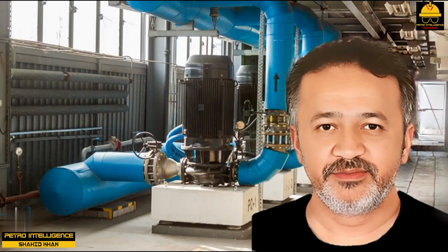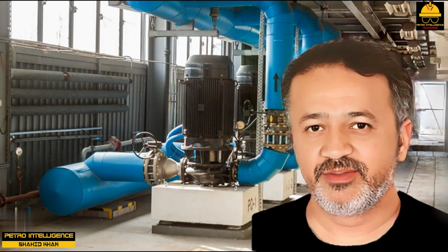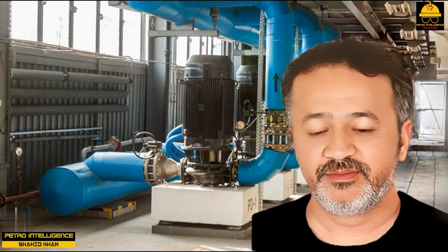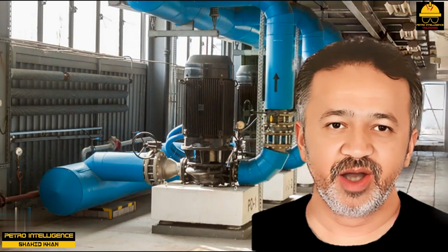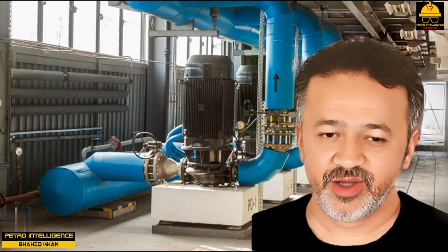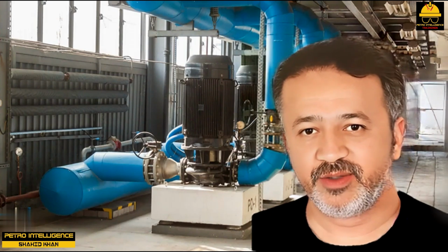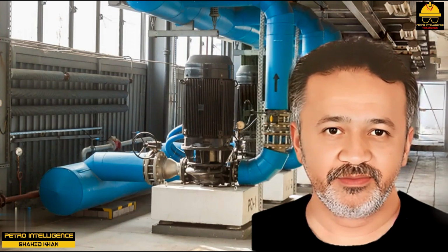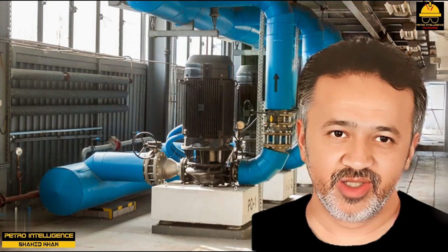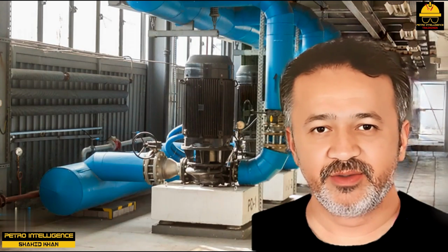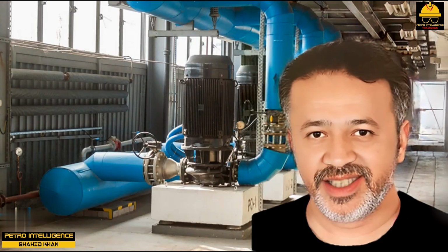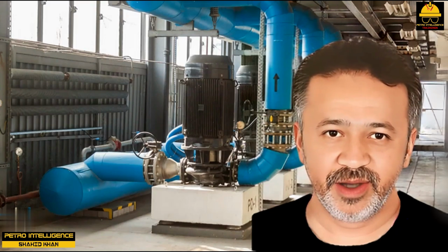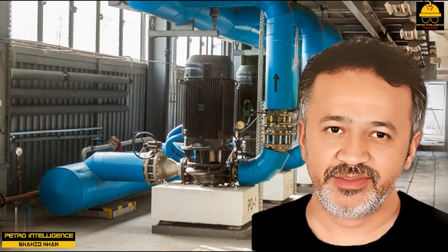Impeller rotation. Motor-driven pumps often are found running backward. If the motor is wired up backward, this is called reversing the polarity of the leads. The pump will run with the impeller spinning backward. This will reduce the pump's discharge pressure, sometimes by a little, 10%, and sometimes by a lot, 90%. It depends on the design of the impeller.